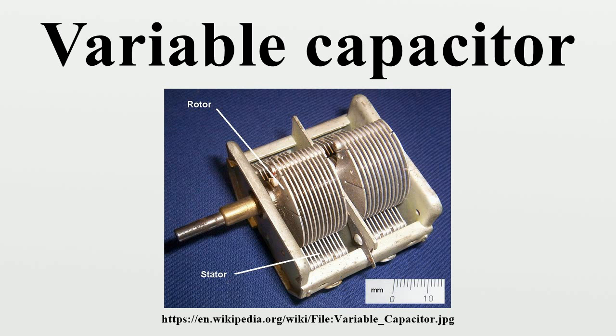Transducers. Variable capacitance is sometimes used to convert physical phenomena into electrical signals. In a capacitor microphone, the diaphragm acts as one plate of a capacitor, and vibrations produce changes in the distance between the diaphragm and a fixed plate, changing the voltage maintained across the capacitor plates. Some types of industrial sensors use a capacitor element to convert physical quantities such as pressure, displacement or relative humidity to an electrical signal for measurement purposes.